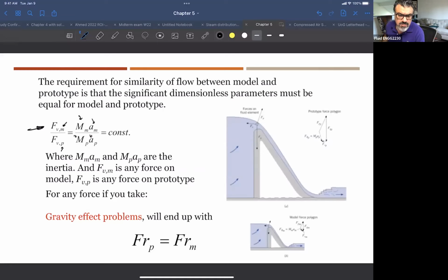I mentioned last time that every dimensionless number that we listed in the table that I started the lecture with is basically representing some physical forces. So for example, flow around dams like this, the physical model here is gravity forces and inertia forces. So the ratio between the inertia of the mass flowing around the dam and the gravity, because gravity is considered to be one of the major important forces that is driving the fluid in this case. So we're expecting to see something called Froude number, and the Froude number in these tables is representing inertial force divided by the gravitational force.